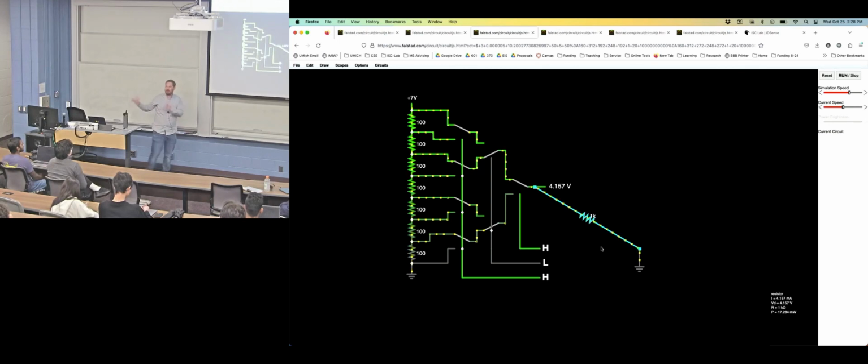So the voltage follower on the output is much like the sample and hold circuit on the input of the ADC. That thing's job is to sample a little voltage and hold it so that it can be analyzed without being corrupted. Here, you don't want your output to be corrupted, so you put in a little keeper, a little voltage follower, to make sure you're able to drive the load. So both of them are trying to deal with this finickiness of the analog world.